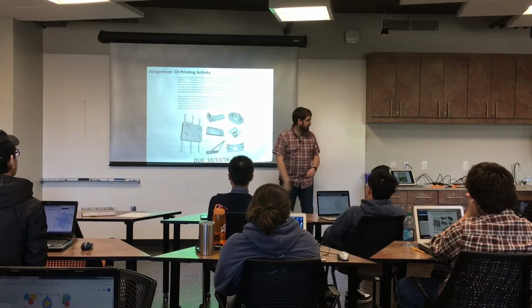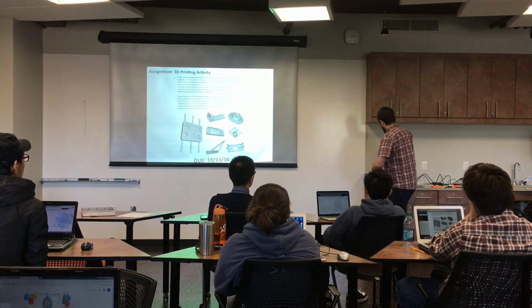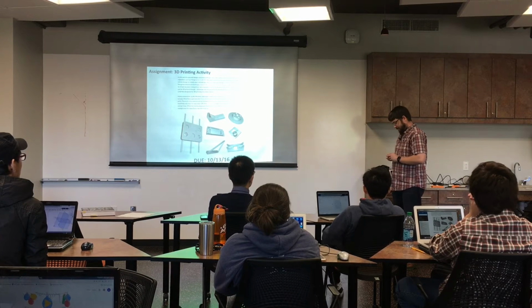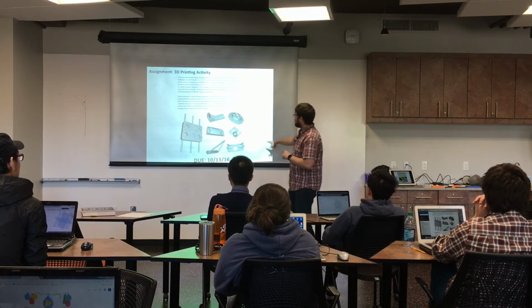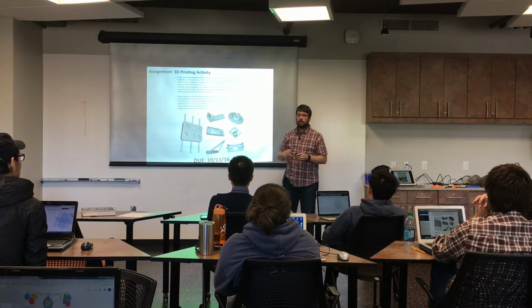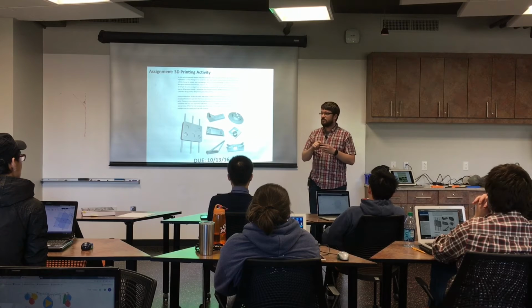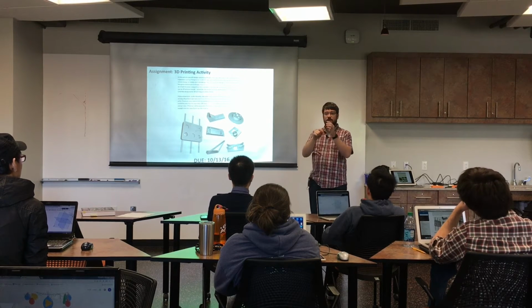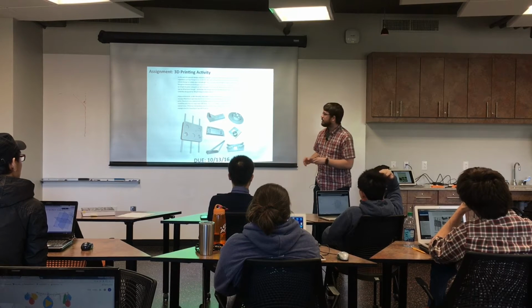This is part of a pulley that is here. I don't know if this is glued together or not. Yeah, this one's glued together. So you print 2 of these. You see it's got these pegs and holes, and they lock together, and you get this nice pulley. That's another trick if you have something that's going to have overhangs no matter how you print it: just cut it in half and make some way to join it.